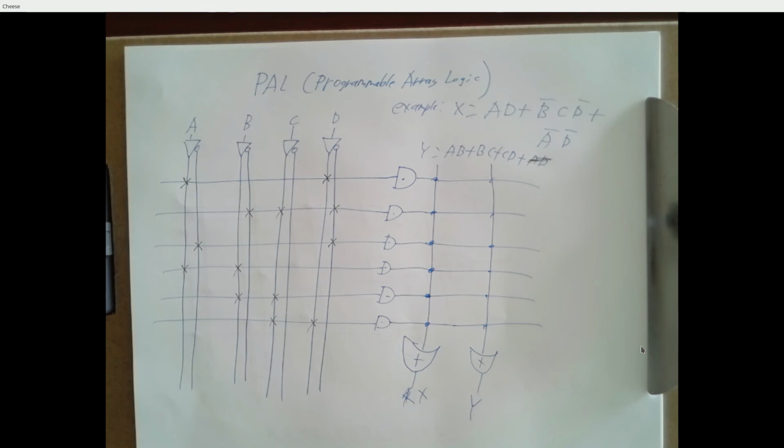So you put a fuse in your electric panel at home. You've got power coming in from the street, lots of current potentially. You run it through wires in the wall to your lights and your outlets and so on. Well, without a fuse, if you put too much current through those wires, they will melt. And if the wires melt in the wall, it's really expensive to replace them. So before the electricity gets to those wires in the wall, it goes through this fuse. You know that these wires can handle 20 amps of current. You set up this fuse so if it draws 15 amps, it melts, and it protects the wiring in the house.